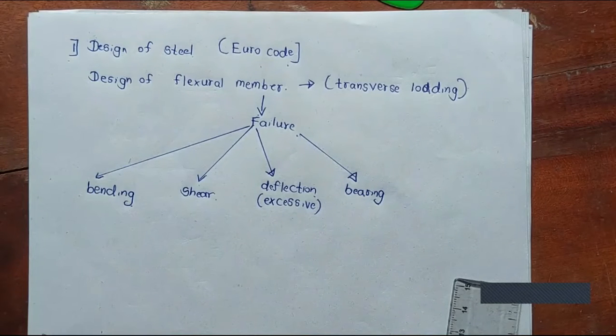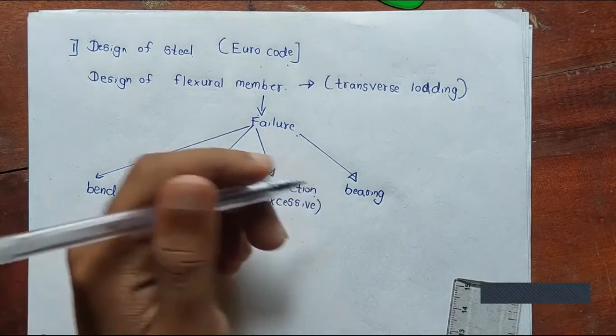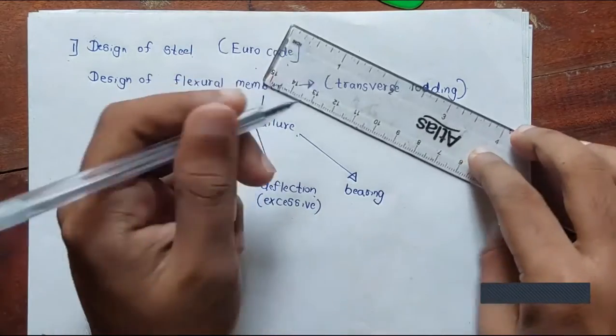Again, when the bearing is bearing, there are stresses in the bearing, and that material will have some limited strength. So if the bearing strength of the material is exceeded, the bearing fails. These compression forces in the bending member can also lead to local buckling.